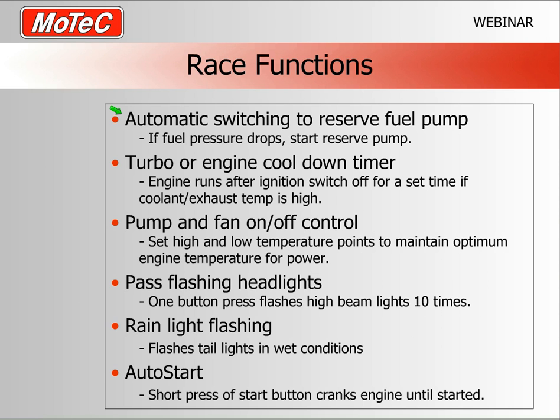Firstly, we can switch to the reserve fuel pump very easily. This might be something that normally the driver would have to be alerted to and throw a second switch on the dash if they lose fuel pressure or engine power. The PDM can monitor the fuel pressure, and it can also monitor the status of each of the pumps, and if the main pump starts to fail or is for some reason causing a short circuit, the PDM can then start using the reserve pump. In addition, it can notify the driver by using an alert on the dashboard, but it can also run these functions in the background.